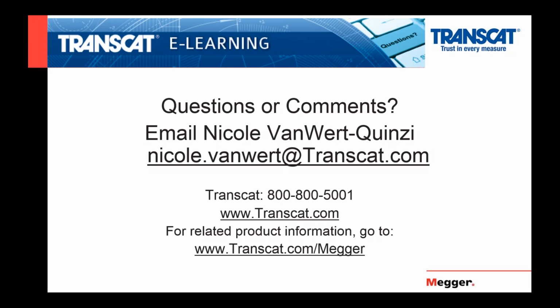Well, you're going to have to recharge the battery first and then probably run the equalization. And again, whenever you're dealing with an equalization, because you are going to be raising the voltage above the standard float voltage, you always go with battery manufacturer recommendations, because the last thing you want to do is void their warranty or damage the batteries. Right.